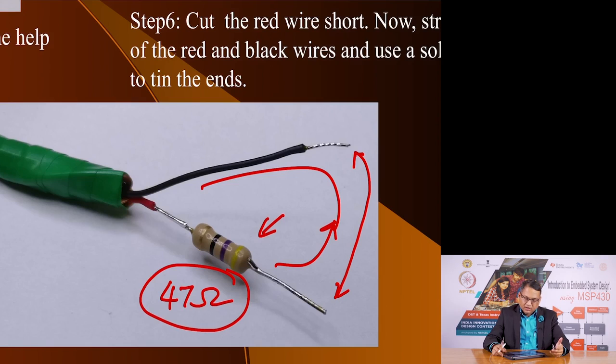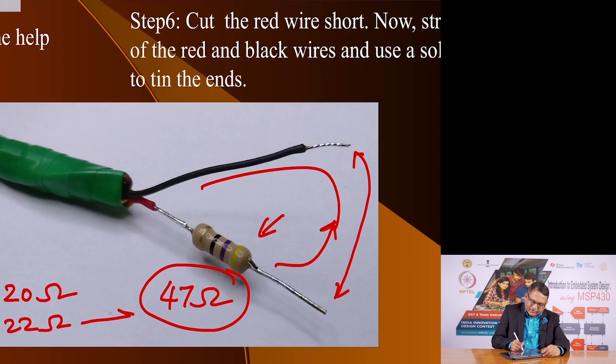If you have a lesser value resistor up to 20 ohm, that is suitable. So, you can choose a standard 22 ohm up to 47 ohm resistor like this, and once you solder on the 2 wires, it provides you 5 volts that you can use safely to power your LCD.